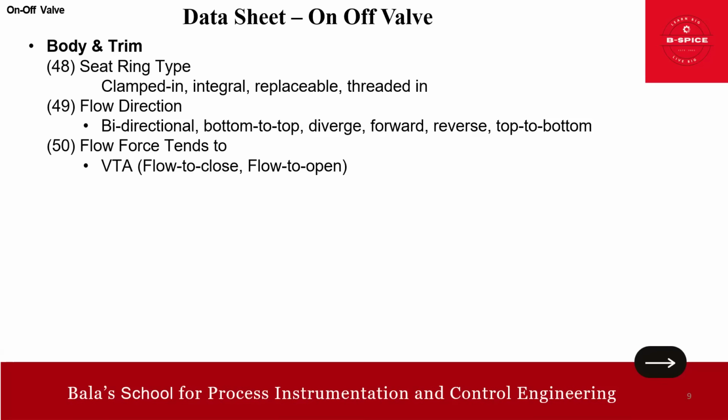That's it, friends. So this FTO, flow to open, is commonly used in general service applications, unless there is a specific reason to go with flow to close, which is for higher applications, I mean high temperature and pressure. So flow to open is for general service. I think this is enough.